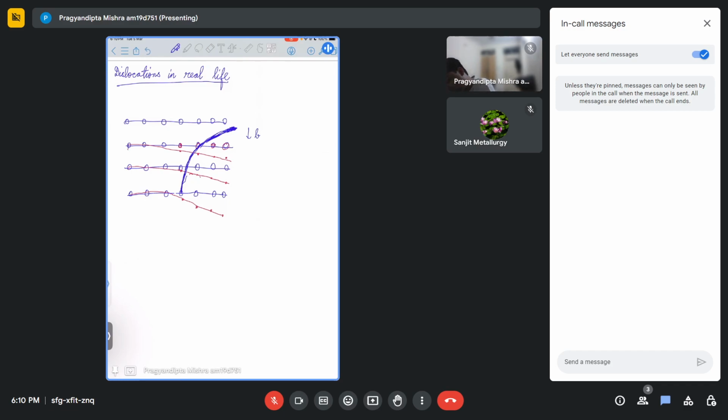Here you can see the dislocation line has become almost horizontal, and the Burgers vector is vertical. So this point would probably be edge. While at this point here, the Burgers vector is also downwards, while the dislocation line is also downwards. So at this point we can observe screw.